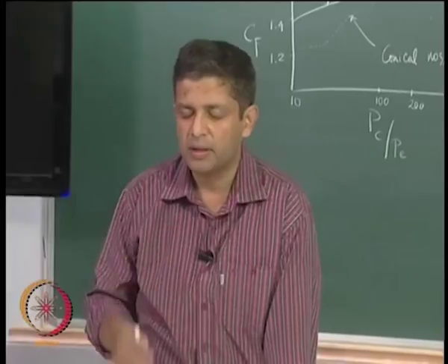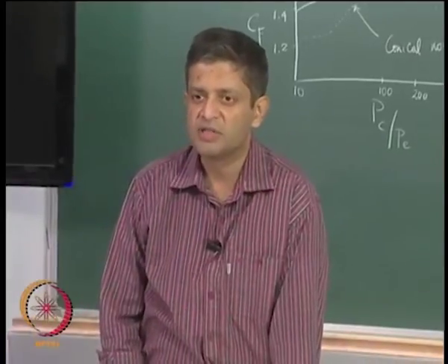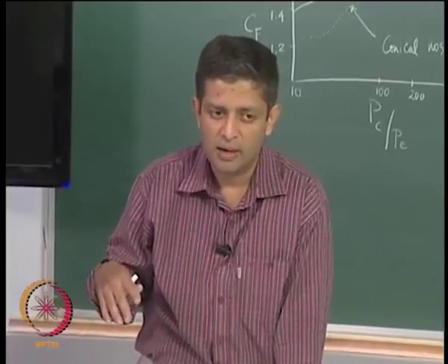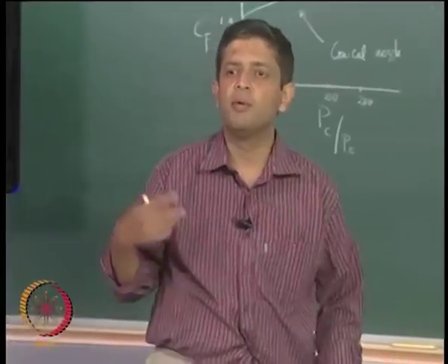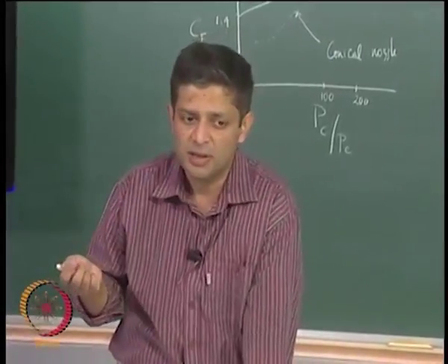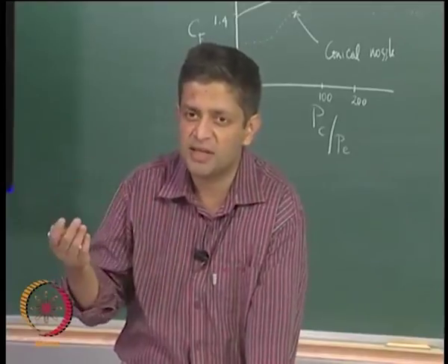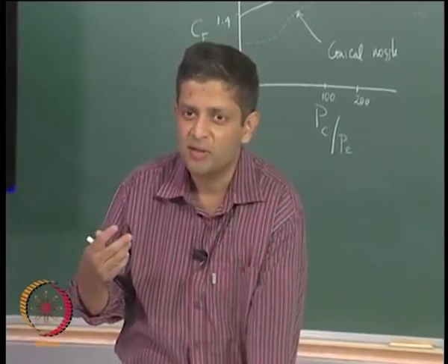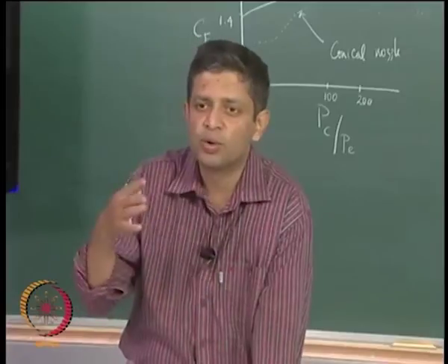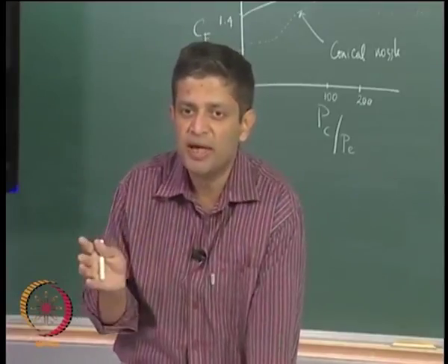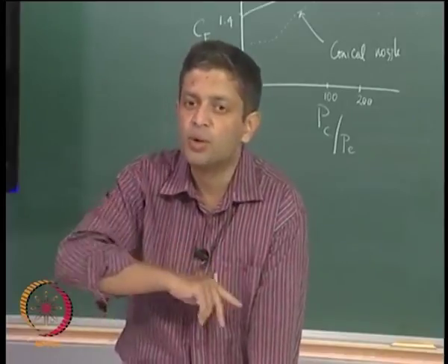If you look at the tactical missiles, these are small rockets, and the level of thrust that they produce, the accelerations that they have initially is of the order of 10 g. So they very quickly go to a very high velocity. Okay. So which is why you do not need any control in the boost phase.